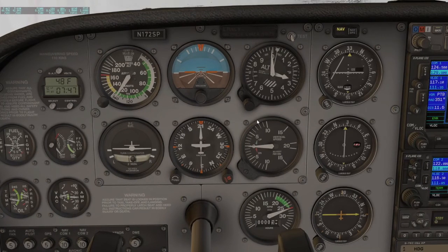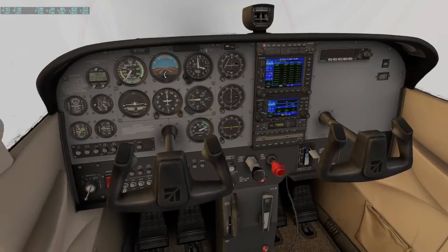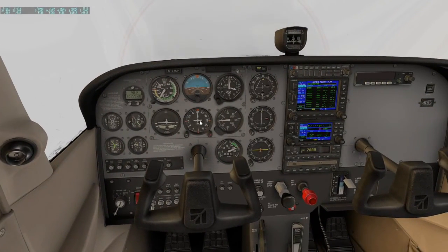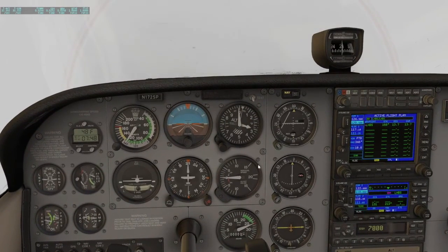When we're done with the interception, I'm going to bring the map back on, and we'll be able to take a look at what we've done and how we intercepted that 300 radial inbound. Again, can't see anything outside, and we don't use the GPS. We're mainly navigating using the VOR, the CDI tuned into a VOR station.